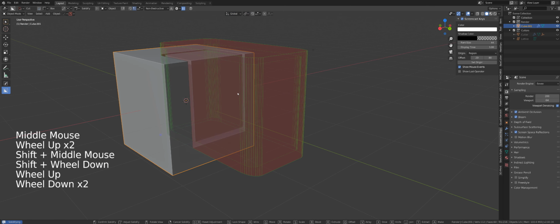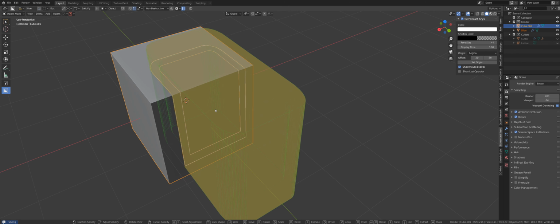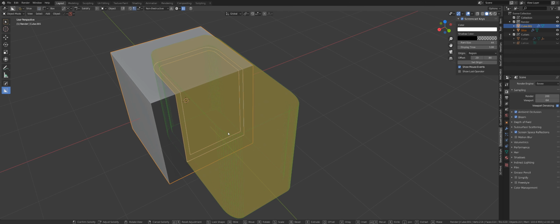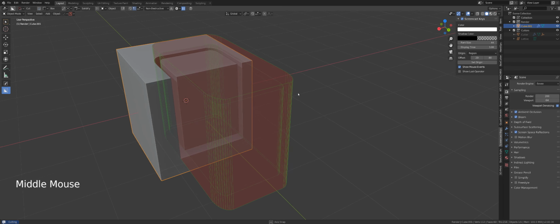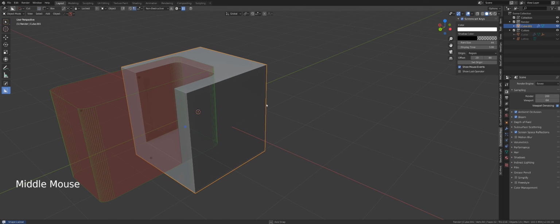Another thing that you can do is press T to introduce solidification, and solidification is going to work with slash like this. So it will introduce a sort of inner part that's going to be slashed out with inset. And by the way, you can adjust or stop the solidification by pressing T. So if I press T, I'm going to stop that. If I press T again, I'm going to start solidifying. And X to go back to my original cutter. T to remove the solidification. Right.